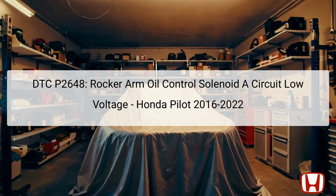The DTC P2648 indicates a low voltage condition in the circuit of the rocker arm oil control solenoid A, specifically for Bank 1, in Honda Pilot models from 2016 to 2022. This solenoid is a crucial component that controls oil flow to the rocker arms, which regulate the movement of the engine valves. When the solenoid is functioning correctly, it allows for efficient engine performance and helps in optimizing fuel efficiency.